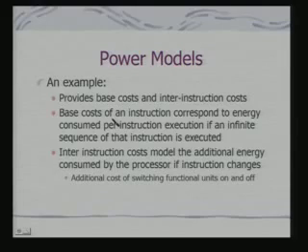What is a base cost? The base cost of an instruction corresponds to the energy consumed per instruction execution if an infinite sequence of that instruction is executed. That is, if you consider an instruction of a processor, and if I want to execute that instruction indefinitely, then there will be a certain power consumption. So that's the base power consumption for execution of an instruction.